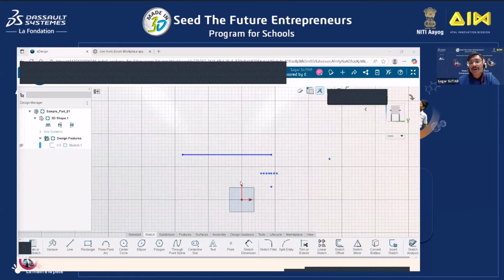We created the point, we created the line. Now you know the third geometric entity: the point is dimensionless, the line is a 1D entity. Now the first 2D entity is the triangle. How can you create it? Just use the line command. We have already created one line. As I hover over this line, you can see a pink or purple color square appearing,